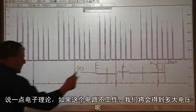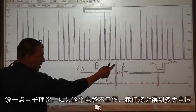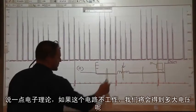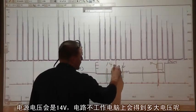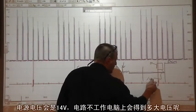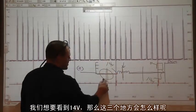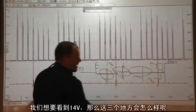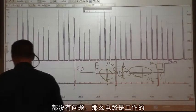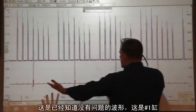Okay, so a little bit of electrical theory. If this circuit is off on this design, what are we going to see? What kind of voltage? Our feed voltage, engine running, is going to be 14. What are we going to see all the way at the computer with the circuit off? We want to see 14 volts. If you see 14 volts at that wire, how is this, and how is that? It's all good.